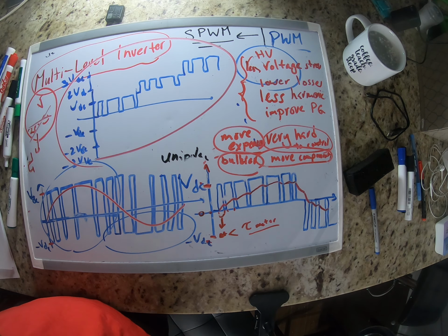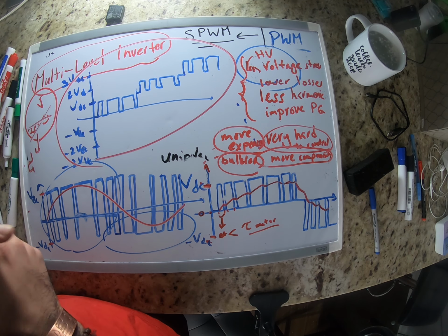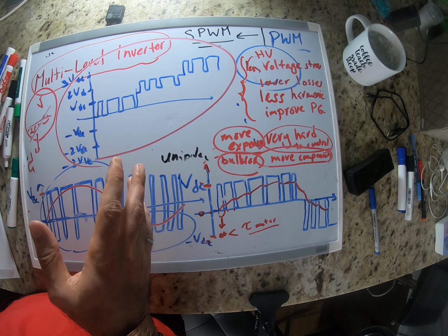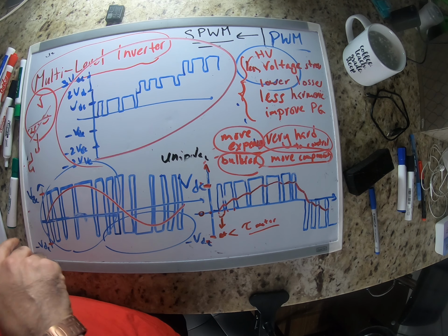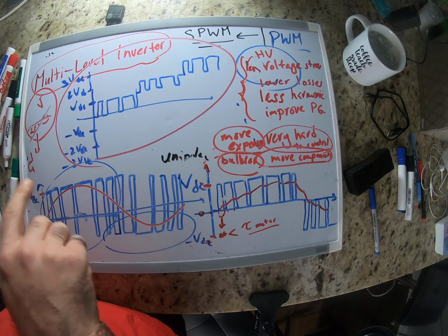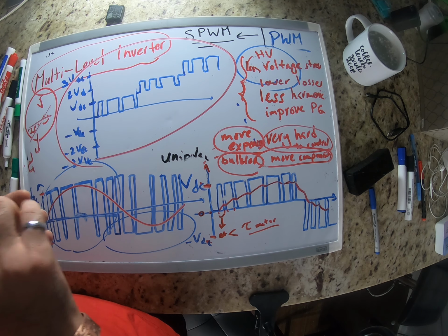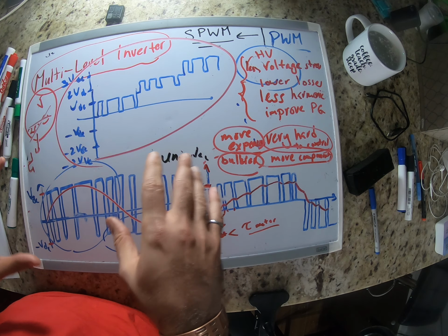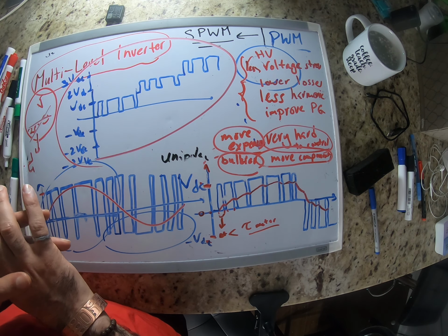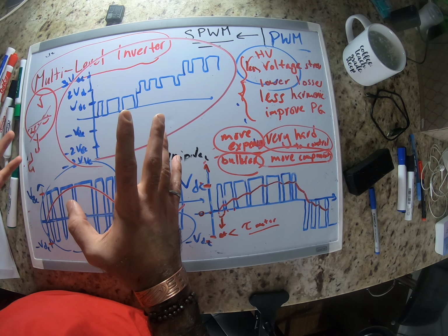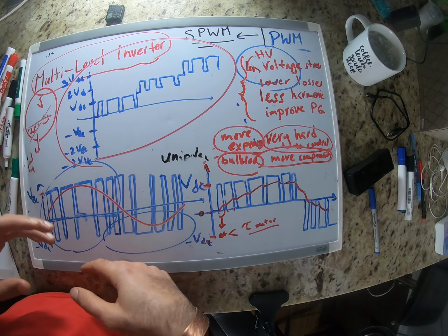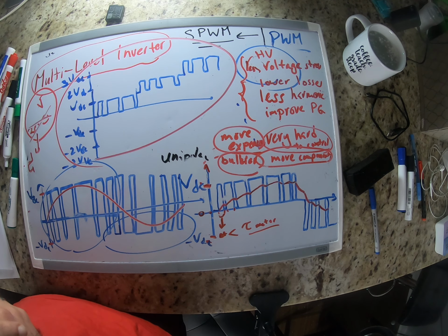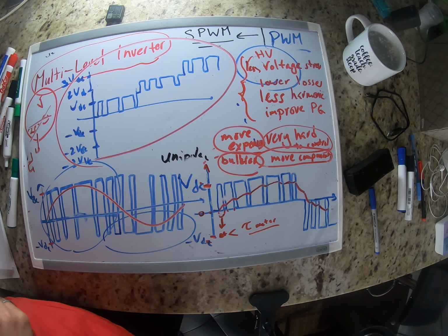What I highly recommend for you guys to do is put a full wave or full bridge inverter, single phase, right? And then draw a sinusoidal wave and a triangular carrier waveform. Similar to what I discussed for unipolar and bipolar modulation, try to create those gate signals, and then from those gate signals try to draw the output voltage. This is going to be very helpful in understanding how PWM works.